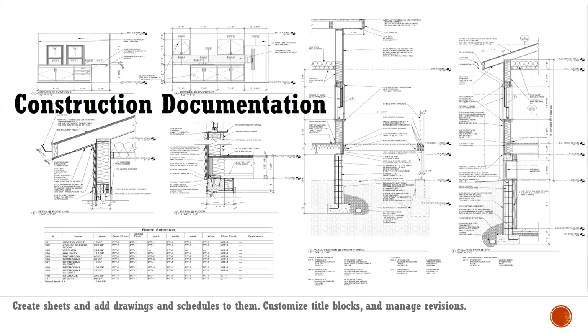All those things may be your identities, and we can customize them. So the first part of BIM implementation will be customizing these kinds of standards in your BIM platform. Just like creating a block, we can create a custom component and use it on any project we are completing. And here you can see this tagging. It is actually automatic. We just have to place the arrow there, and the information will be provided, and we can customize it so that when I place the tag, all this information associated with the model is created there.